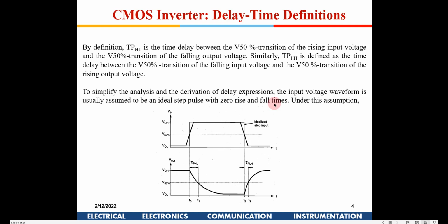Generally, if you are doing it like we are doing it in LTSpice, we just have the single NMOS, whereas if you are doing it for an actual fab lab, in which you have an MOU or something where finally you are going to fabricate the chip, then they will give all three kinds of devices, like NMOS fast, NMOS slow, and NMOS typical. In GPDK also, I think all three devices are available if you are doing the general purpose, because when you go to the simulation setup in Cadence, you have the SS and such kinds of setups available, which will select the necessary model file accordingly, the slow and the fast models.